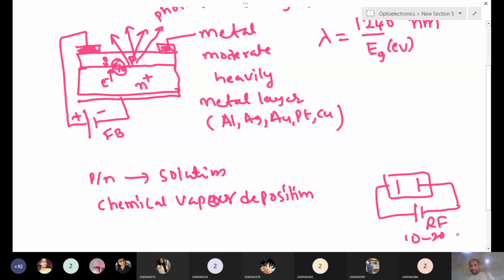In between the electrodes, plasma will be created when we send some gas into the chamber. First we send gases into the chamber and give the RF power. We ionize these gases and plasma is created. This plasma will be deposited on the substrate we keep there.